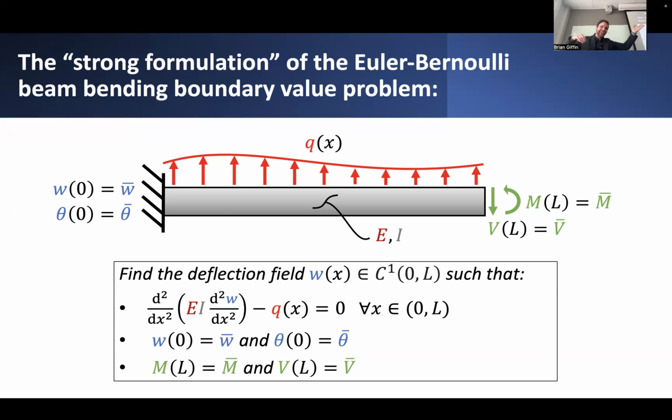So the left-hand end and the right-hand end are what I'll call the appropriate boundaries of this beam. Certainly, we have some distributed load, but for the purpose of the analysis, it appears more like a body force than an actual boundary traction. So we can treat it like a body force and treat only these ends as the boundaries of this beam.